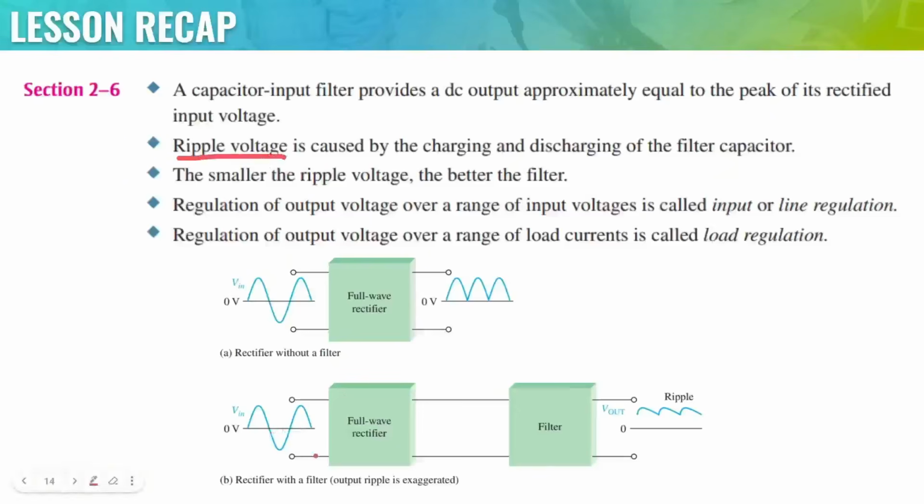When we convert an AC to DC with a full wave rectifier, at this part of the process, it's not actually going to be a flat line yet. There's still going to be a little bit of ripple or unwanted AC. Normally, the ripple from half wave rectifiers is bigger compared to full wave rectifiers.